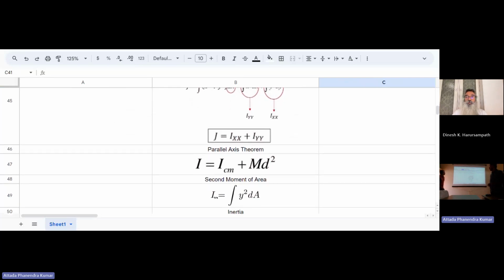This basically applies for I-beams, where you're calculating, I believe, the sigma area. If they include that, this is the reason why I-beams would be superior in some sense to a normal solid block, as it can provide a higher inertia by including the Md squared term.